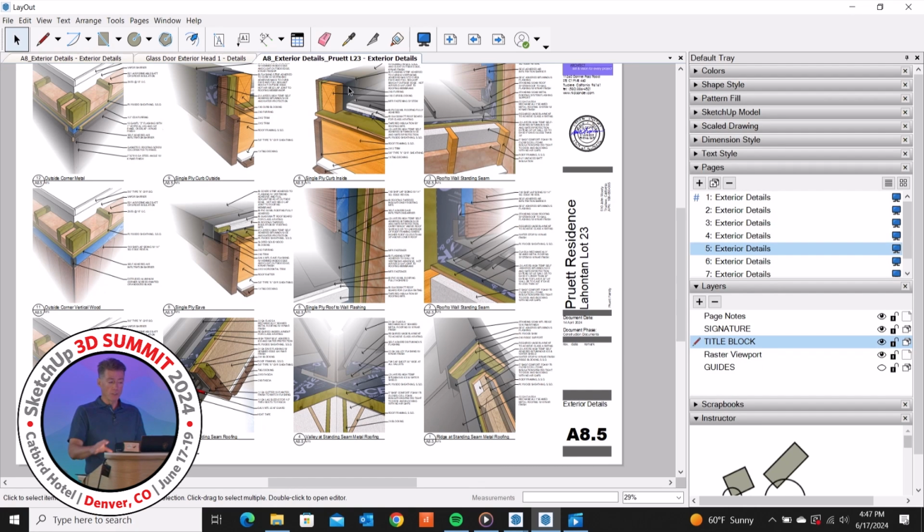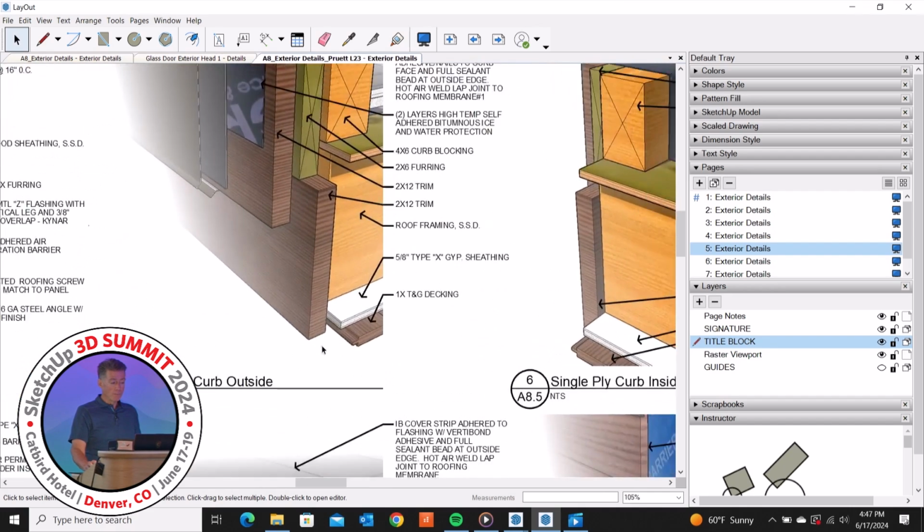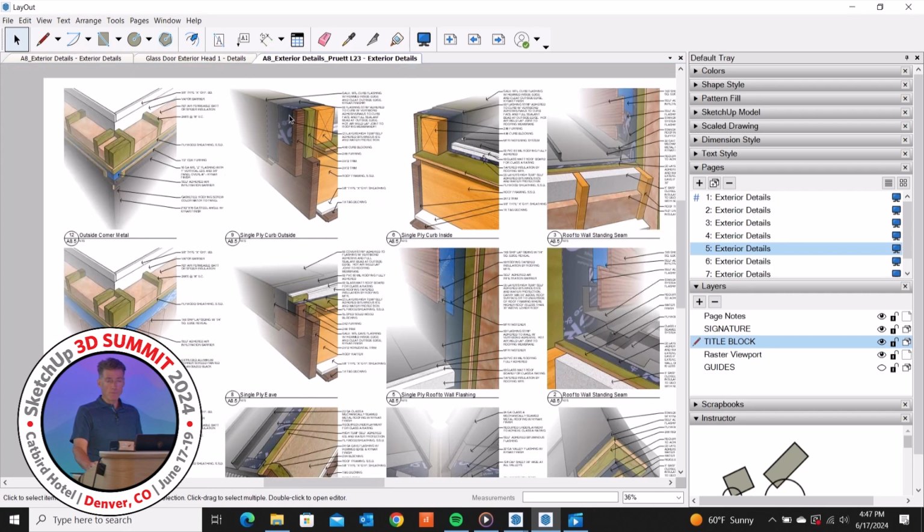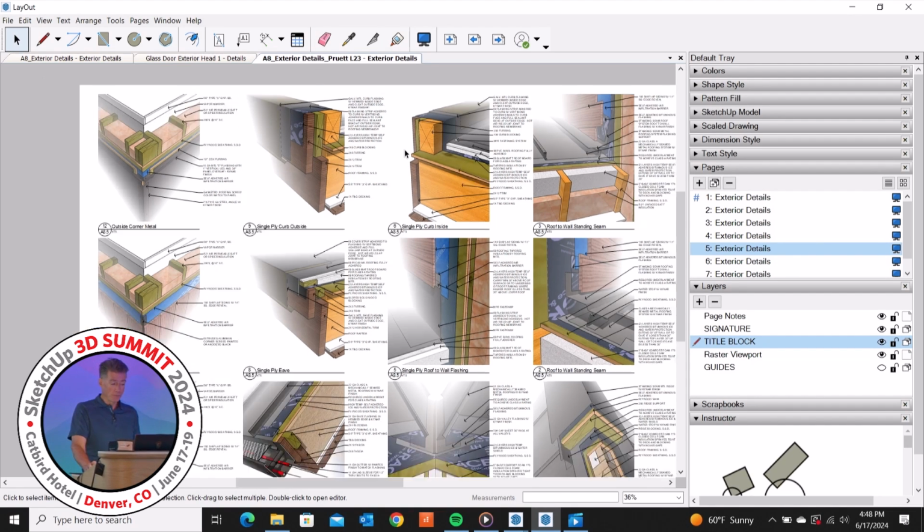And that gives it a nice clean look on the outside of the curb where it also has that cleat to a nice deep fascia on the end. And that fascia can vary in depth. I'm showing it built up with a 4x6, but it depends if we have a really long run or a deeper gravel or stone ballast, then we will lift that up as required. I just have to explain that to them usually in the field.